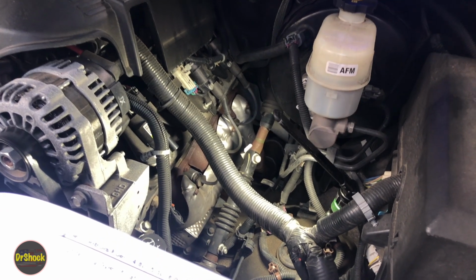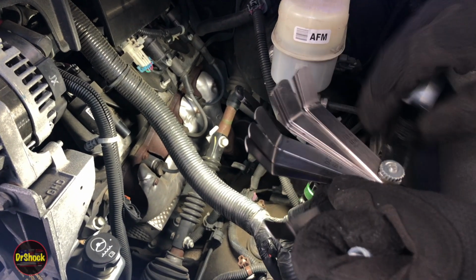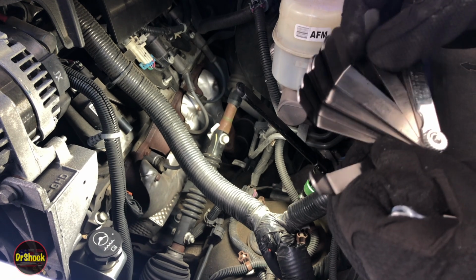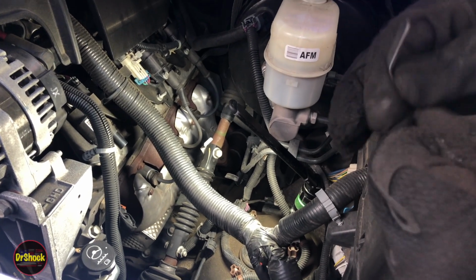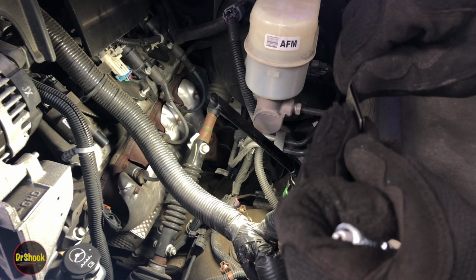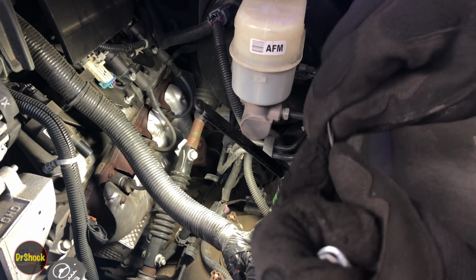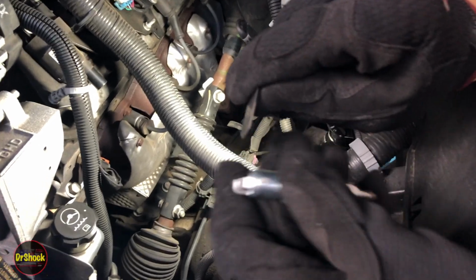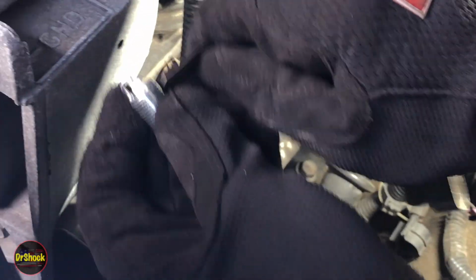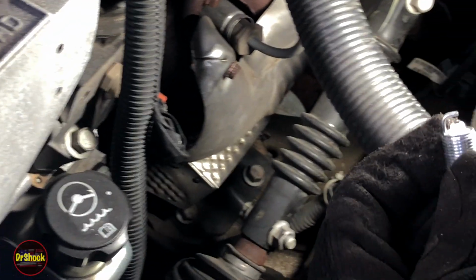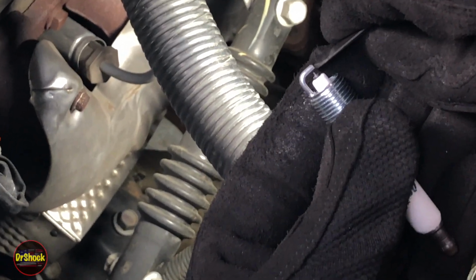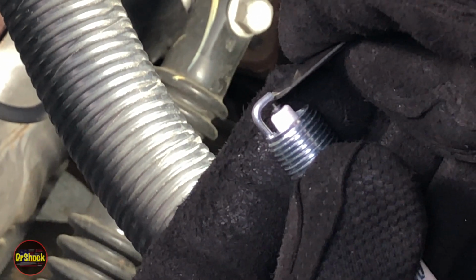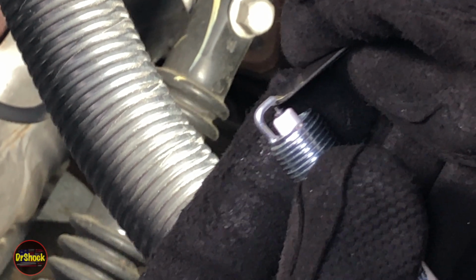I'm going to pull a feeler gauge over here, and I'm going to set it to what the factory setting is for this particular plug for this particular engine. Right? Different plugs have different gaps for different engines. 40 thousandths on this guy. And you don't ever want to stick a feeler gauge into an iridium plug. I'll kind of get him over here behind something where you can see, yep. And we're just going to hold this next to it. And you can just eyeball when we're zoomed in. That's like dead on 40 thousandths.